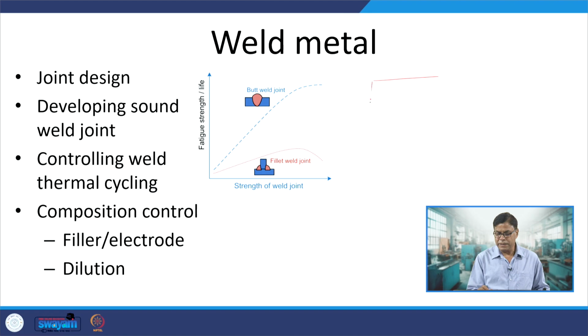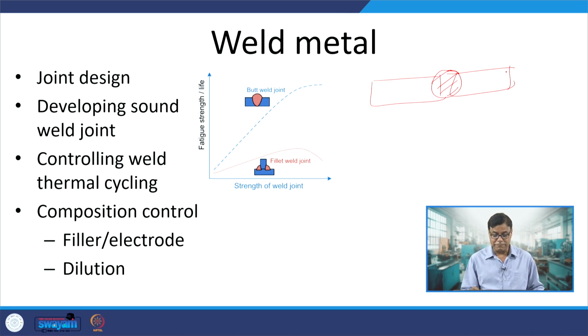The weld joint in general in the butt joint configuration offers the maximum joint load carrying capacity and maximum joint performance, because inherently there is no stress raiser for this kind of arrangement as compared to the fillet weld. Fillet welds under identical conditions offer lesser strength due to the inherent stress concentration present at the toe of the weld. Okay. So, here, say in the T weld joint, this is the fillet weld.